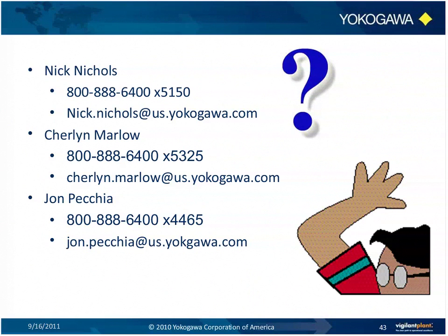Okay, great. Thanks, Sherilyn. We do have a few questions here. First of all, if I'm measuring a pH and an ORP at the same time, if I perform a pH calibration, do I also need to perform an ORP calibration? It is common for these types of systems to have 2 independent asymmetry potentials. So when you do a pH calibration, the asymmetry potential that is corrected does not automatically correct the asymmetry potential for your ORP system. So it's just good practice to follow behind and do an ORP calibration.